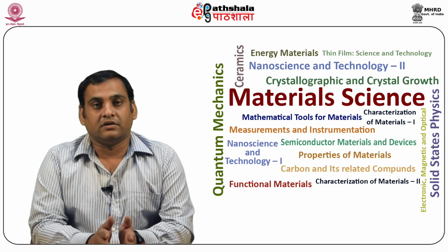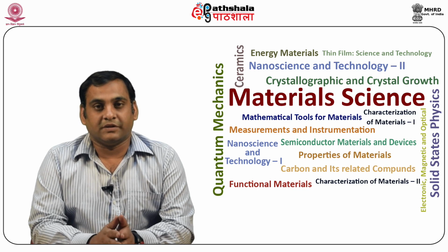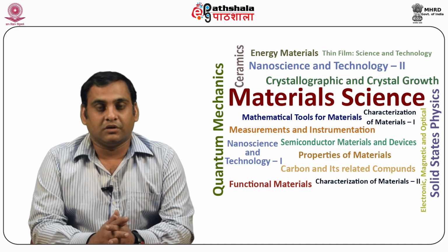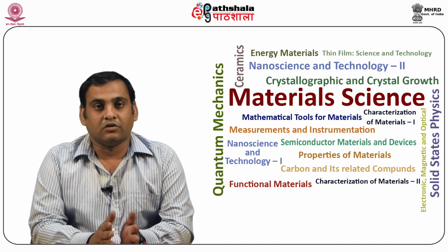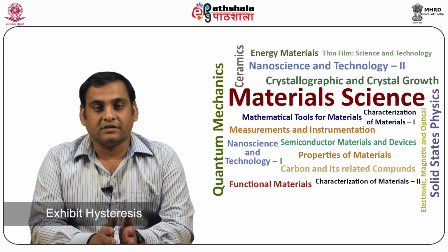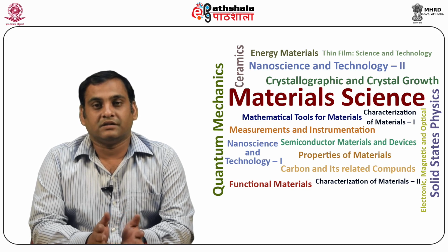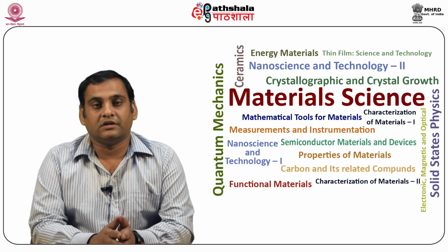Energy in an external field. To extend the energy expression of a point dipole in an external field to ferromagnetic materials, it is not adequate simply to fill the inductor with a medium of permeability μ, because ferromagnets are generally nonlinear. B is not equal to μ0 H. They exhibit hysteresis, so that the energy needed to prepare a state described by B and H depends on the path followed.